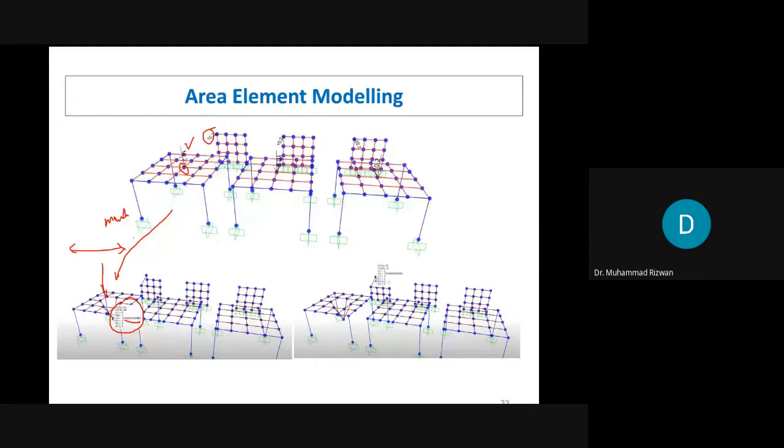Infinite, it is like in millions of meters, for example, because you have applied a loading, but this member cannot resist any out-of-plane loading. If you apply a load in this direction, for example, here in the x direction in plane with the membrane element, then this membrane element will be able to resist the loading.